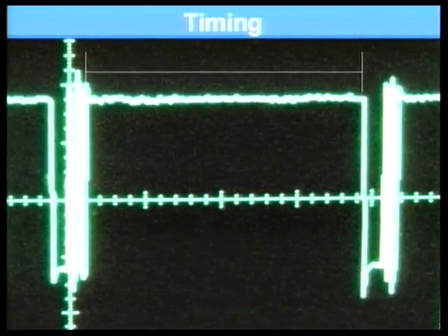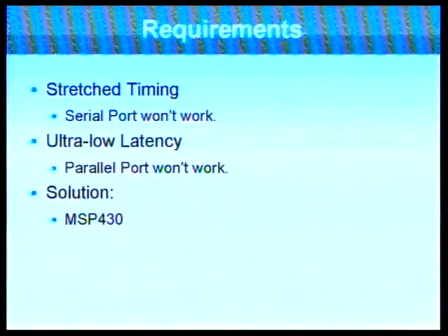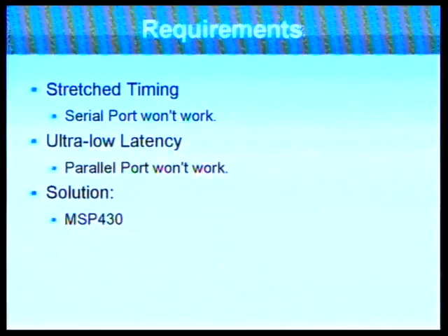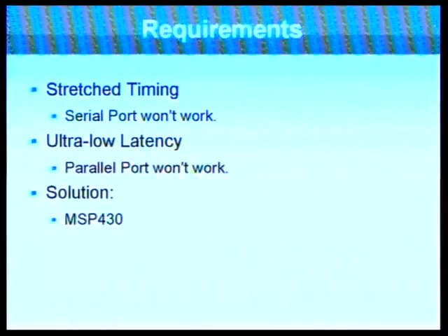So to crack it, again, getting back to the timing, we need to stretch our timing for reasons that I'll explain in a bit. Specifically, if we send bytes which are the proper distance apart from one another, then the victim chip will wait for bytes.